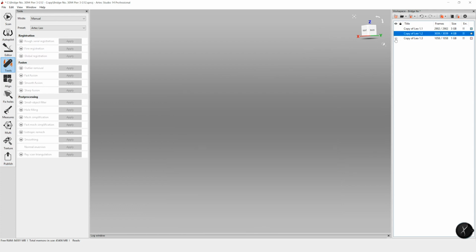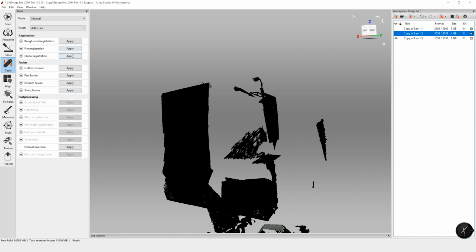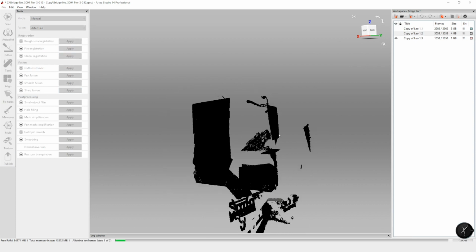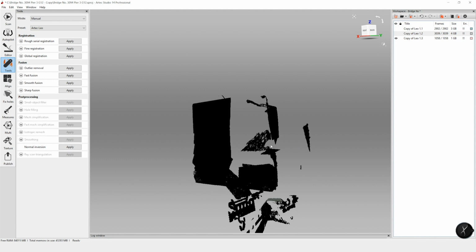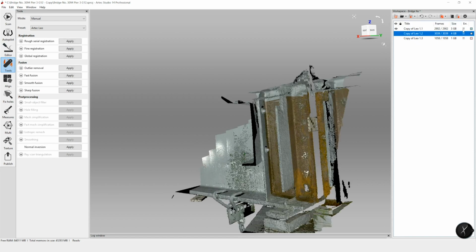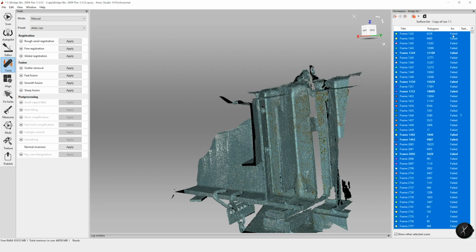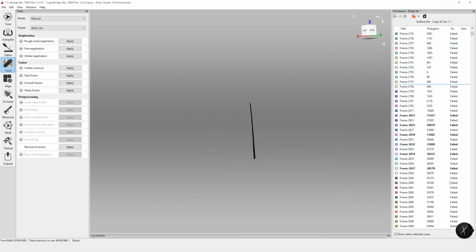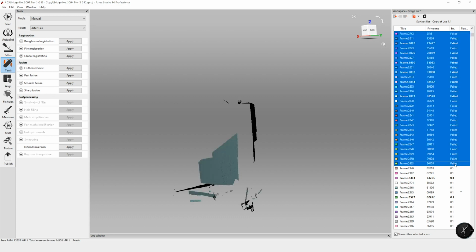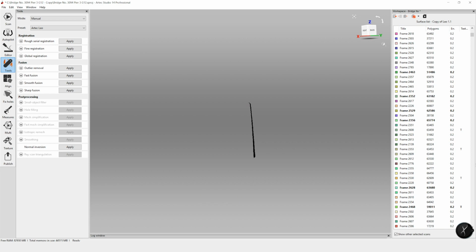You may want to set aside some time when you have other tasks, do each of these components, let them run, and then start the more intensive process where you have to have user input. Once the global registration process is completed for each of the scans, you're going to see those error numbers again. What's different this time is we're going to set a lower threshold for the error that we're willing to accept. In some areas, if there's a larger error and it's one of those points being used as a tie point for the scans to really bring it together, we could have some issues.